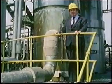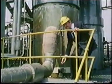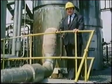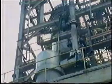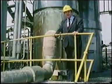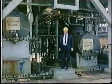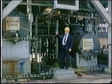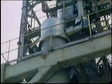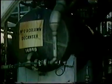This distillation column has been designed to return the acetic acid out of the base back into the reaction kettle, and at the same time the overhead vapours from the top of the column are ethyl acetate and water with no acid in it. This acid-free vapour, coming from the top of the column, passes to the condenser cooler, and it comes out of the bottom as a cold ester water mixture along this pipe into the decanter, where it separates into two layers.